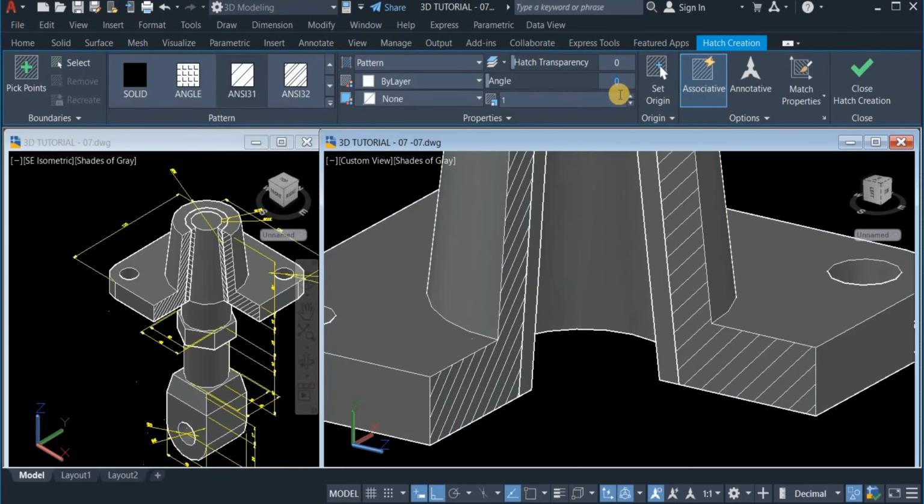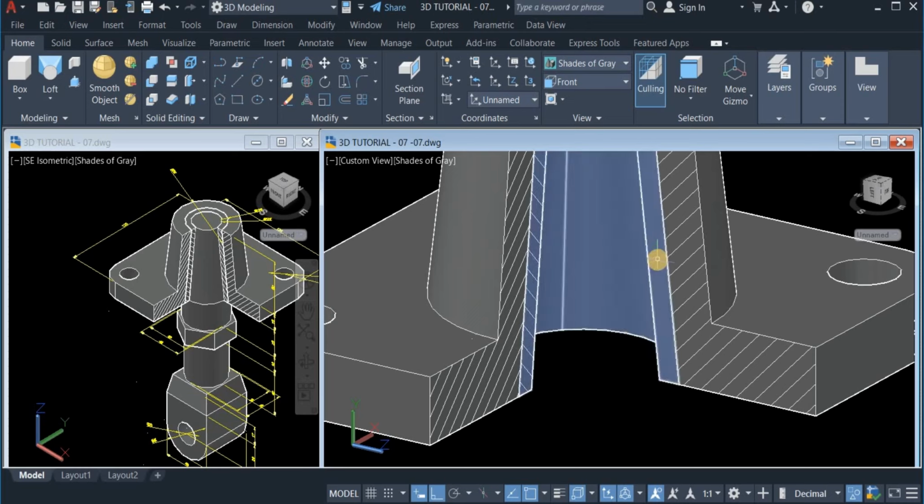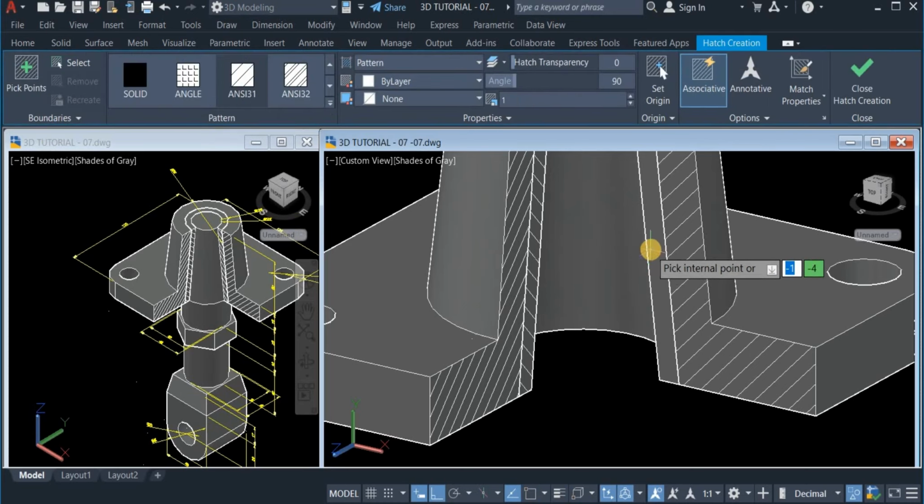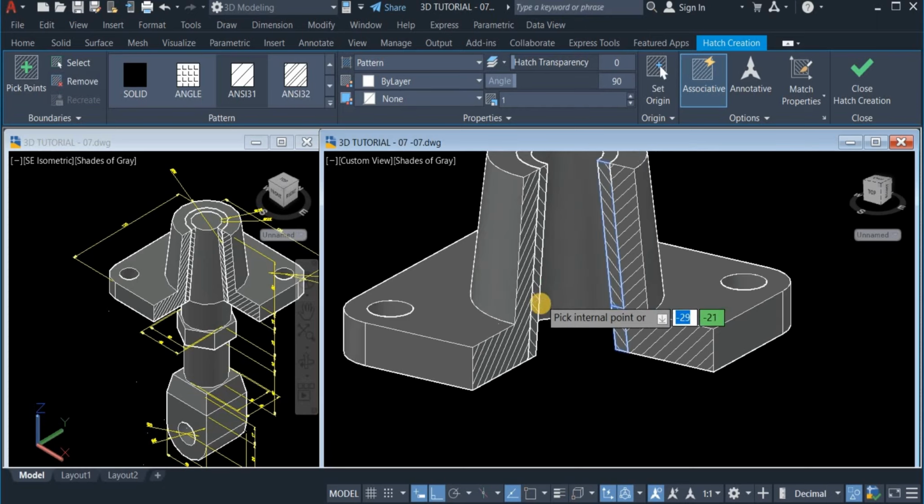Now change the setting to 90 degrees. Then apply on this face. Also apply this. Okay, enter. Now do the same for here. Click on this. Click on the face I want to hatch, which is this, and pull back. Alright, now again, click on the draw panel, click on hatch, and click on this face, and click on this. Okay.